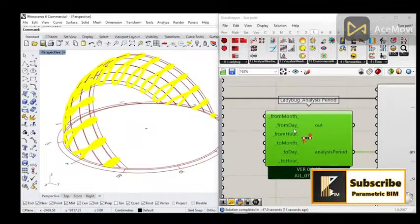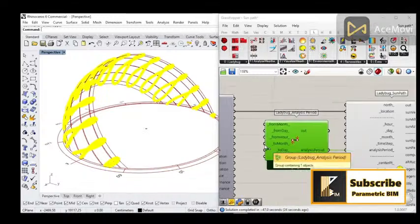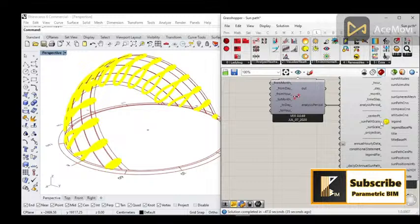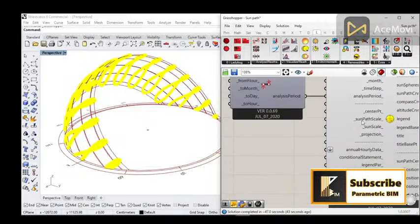But you can also give any month, any day, and any hour: from month to month, from day to day, and from hour to hour. Okay, another thing to show you is the sunpath scale. If your building is a little small or something like that and you want to control the scale of the sun, you can control that from the sunpath scale or the sun scale. Maybe we need to make it smaller.